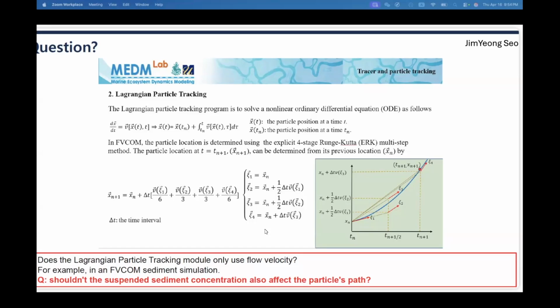Before we only had the Lagrangian particle tracking offline model, but now we also have the offline dye model. For this dye model, we can first run our physics model to get the horizontal velocity and the coefficient like Kh, and then use the existing physics field to run the offline dye program. In this way, you can save lots of time.